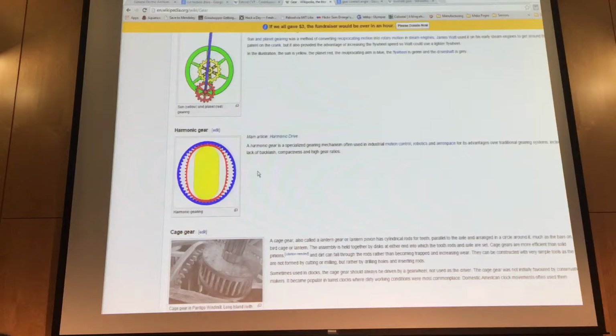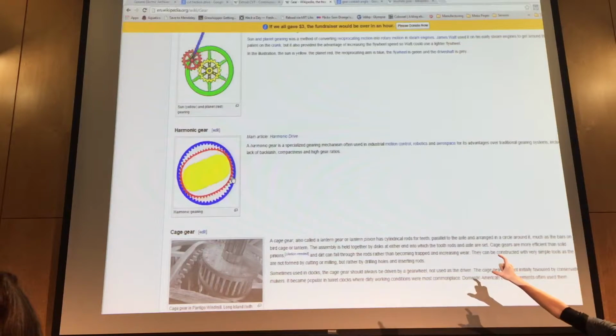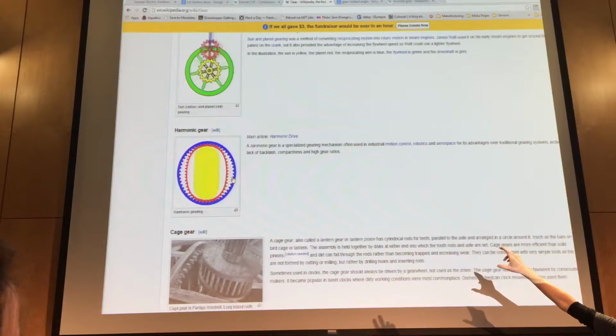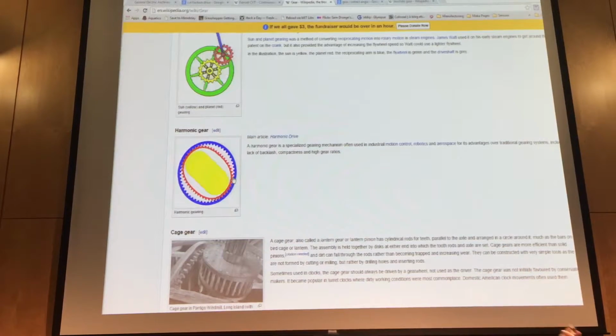There's other systems like harmonic gears where you preload, you stress the gear teeth into each other, and so you only contact in these two spots as you're rotating around. You flex this internal flex spline, and that prevents the backlash from happening. But you also have a very inefficient drive system because you're preloading the system. You're adding a bunch of stress into it. So these things only operate at like 65% efficiency.